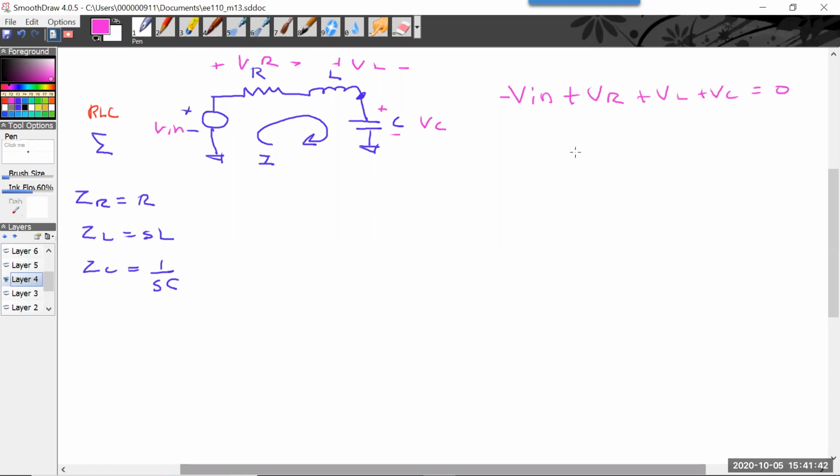They all sum to 0. Or we could just write it this way. Notice it doesn't matter the order they're in. V_n will sum to all three of these voltages. And so in fact, that's why this can be used as a summing technique, even though it doesn't have an op-amp.